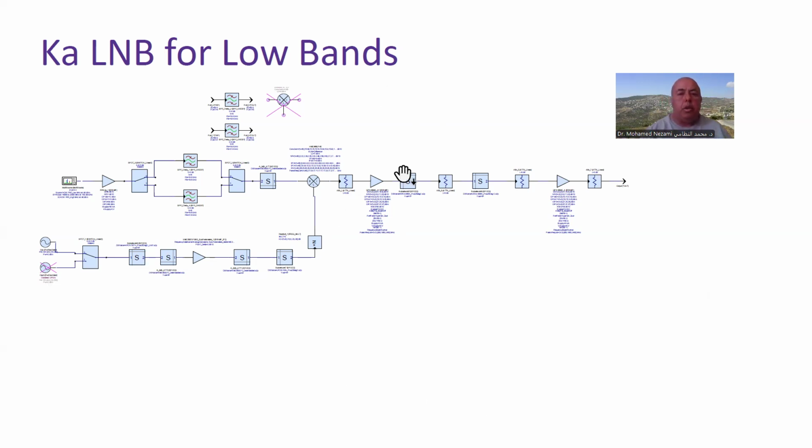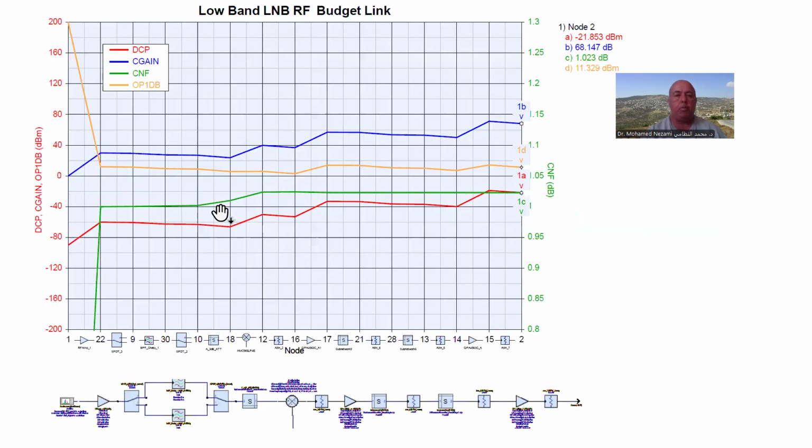All right, so what I'm going to do is sweep and look at the overall frequency response, the conversion gain. Then I'm going to sweep the complete system with a fixed LO, sweeping the RF input level, and compute the noise figure and gain and other parameters as well. And then I'm also going to sweep the input power level to see the dynamic range of this receiver. That's what I'm going to get to next.